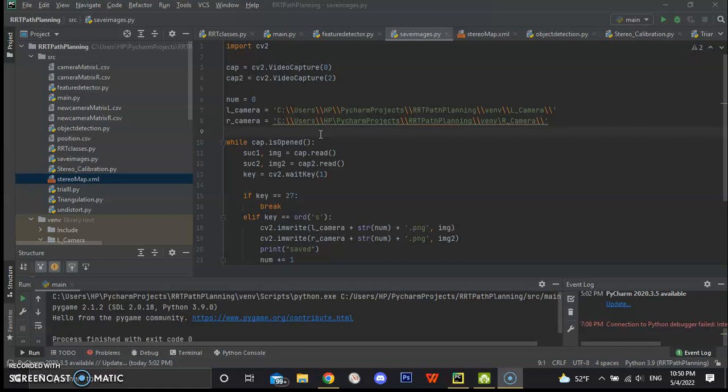It is designed for efficiently searching non-convex higher dimensional spaces, and it is constructed incrementally in a way that quickly reduces the expected distance of a randomly chosen point to the tree. So in layman's terms, once you give the algorithm a start and an end point, it randomly generates samples across the entire map and ties each sample to its nearest sample, creating a node and mapping the Euclidean distance. It does this incrementally until it reaches the goal point.